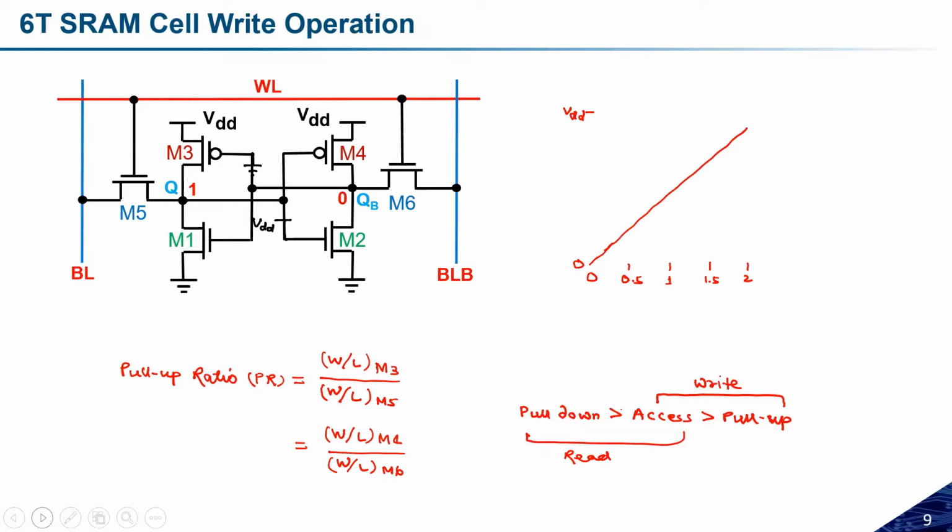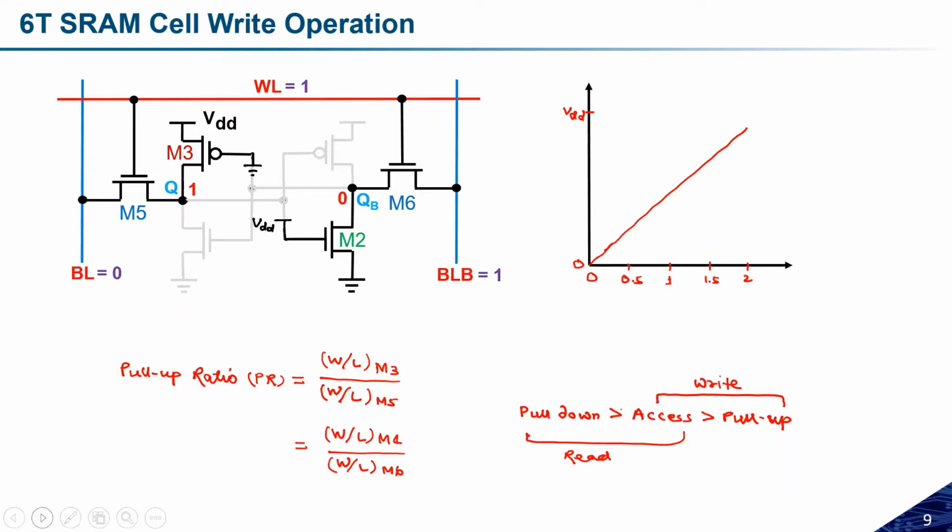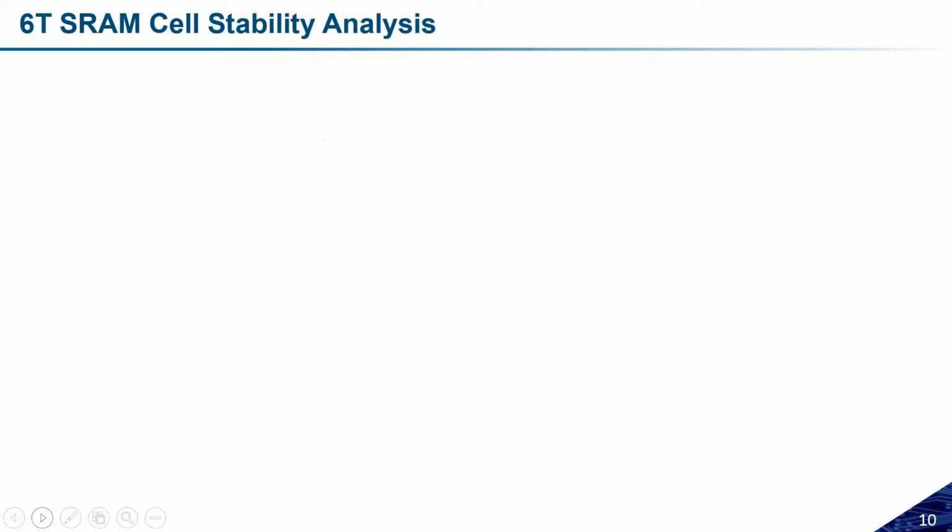Suppose you want to calculate the write noise margin or read noise margin. In that case, how do you calculate it, how do we need to sweep the data at the storage node so that you can get a butterfly curve? So here I will be discussing something like that. Let us try to see.